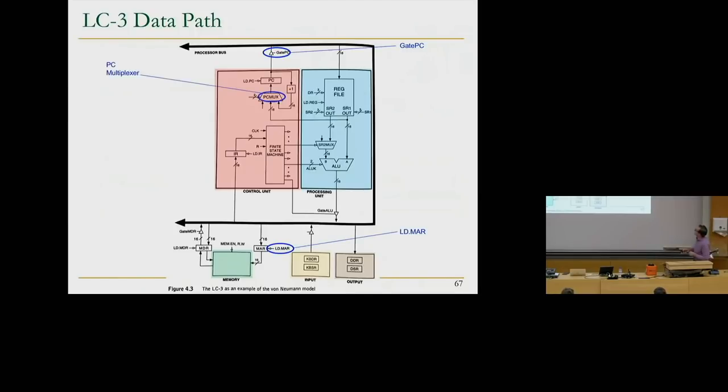Yeah, actually, how do you implement jump in LC3? Let's take a look at it. This is our program counter over here. We already discussed gate PC. But if you want to actually implement jump in LC3 to a register, during the execute stage, what needs to happen is you take the source register and basically load the program counter with it. That's it. Makes sense, right?